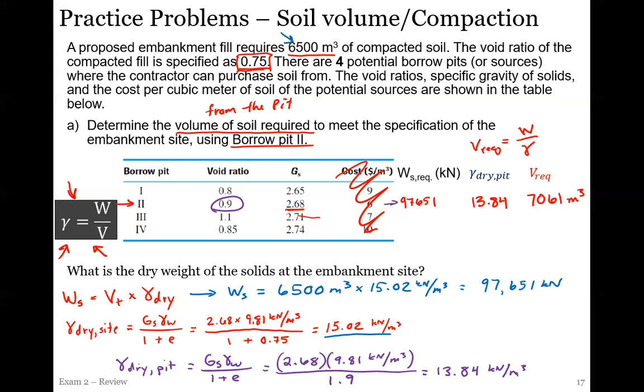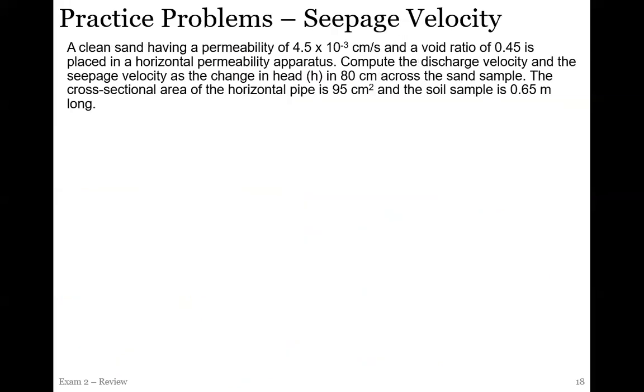All right, moving quickly here. Seepage velocities. We talked about seepage velocity. This is using 1D flow here. This 1D flow is the same as Darcy's, it's just without the area. So the lowercase v is technically the same as Q equals KiA, because if we multiplied each side by A, then we would get Q. So velocity times area is our flow, Q. So Q equals Av. That's where that's coming from.